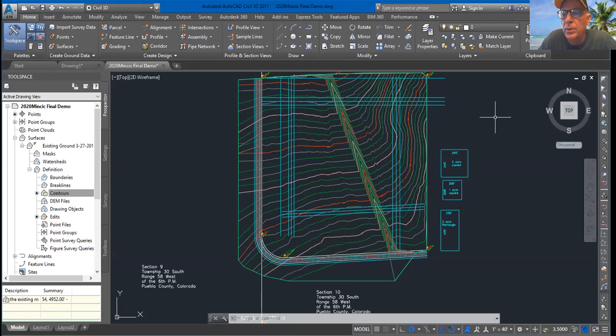The subdivision requirements would require that I have a main street or a main thoroughfare where the majority of the traffic would go, and then secondary roadways. All of the other roadways would be secondary. What that means for us is we would have to look up the regulations for the city government. In this situation, I'm just using some arbitrary rules that I have developed myself. One being that a main roadway is going to be 80 foot wide. A secondary roadway would be 60 foot wide. That would be shown here by the lots I'm showing, representing the sizes of 60 foot roadways and 80 foot roadways. Okay, so knowing that I'm going to be using mains as 80 foot wide roadways.